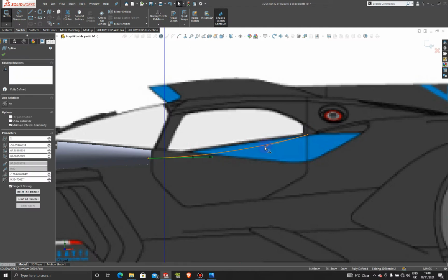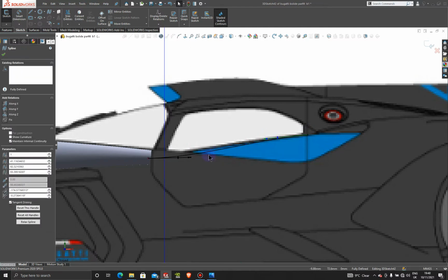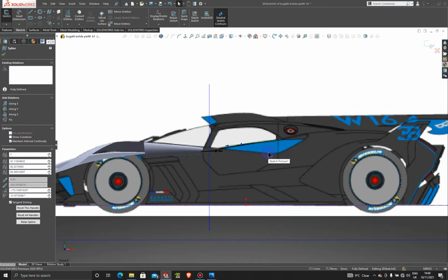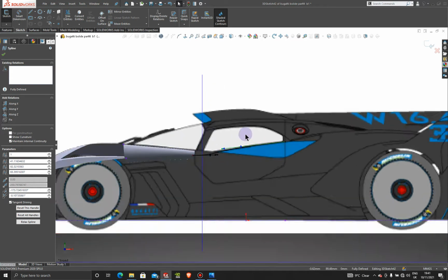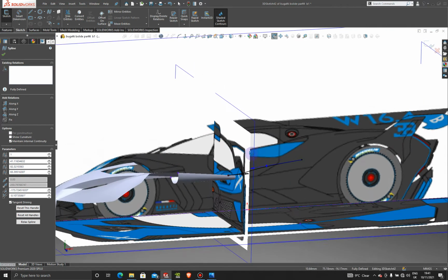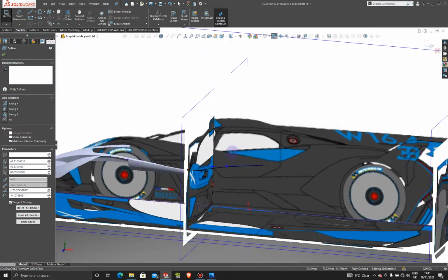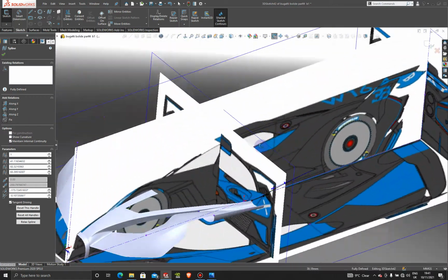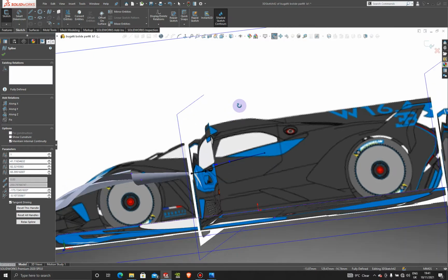So edit this spline. Double click on it. And then we're gonna grab this handlebar and just pull it until we have that curvature we're looking for. So you can see it from this edge how that line goes, and that's exactly how it will go. All right, and if not, we will change it.